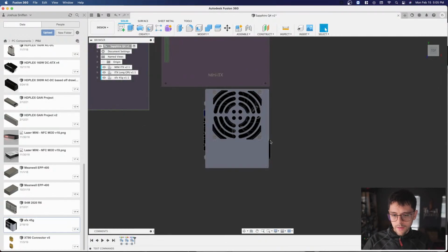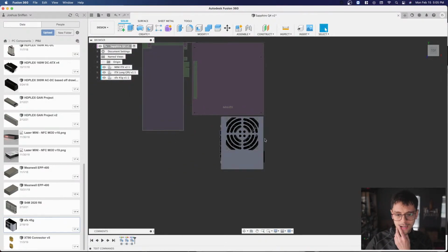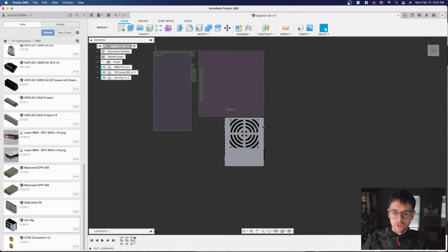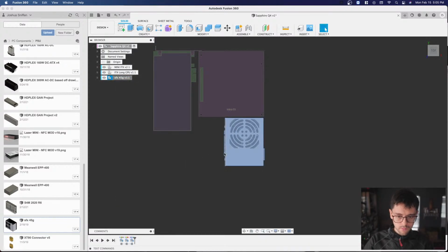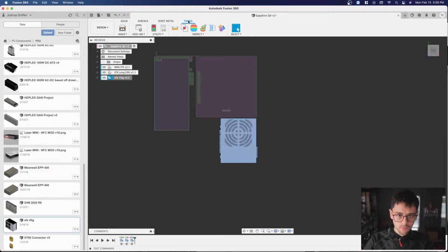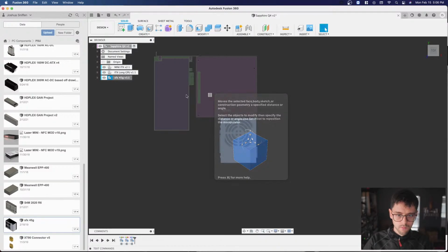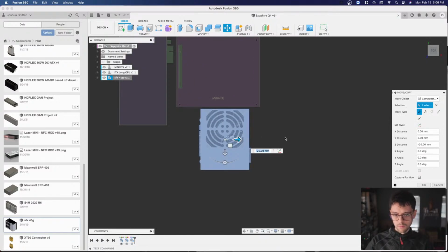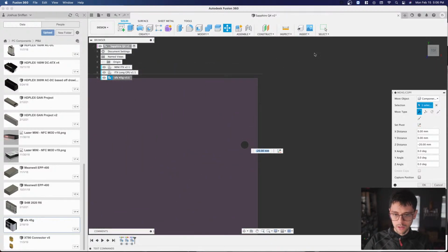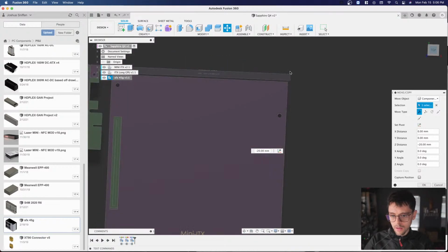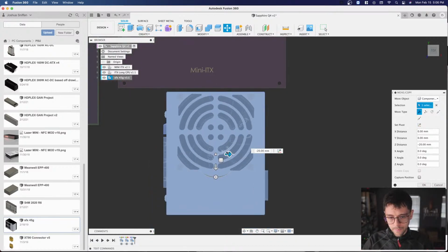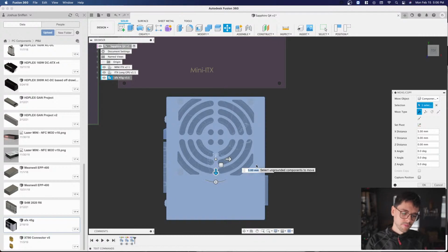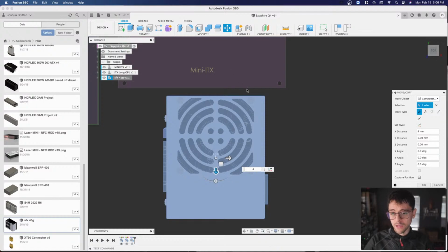All right, so I know that the cable for the SFX power supply is going to extend out about 25 millimeters. So I need to make sure that I am offsetting the power supply a little bit. I'm going to do 20 millimeters because I know I need at least 5 millimeters for the cutout of the I/O shield right there. And I know that I'm going to need a little bit of space right here on the edge of the board for my 24-pin connector. You know that little clip that goes on the end? I'm going to need some space there. So I'm going to actually offset this by 4 millimeters. It was already a little bit offset. I'm actually aiming for maybe 10 millimeters total.